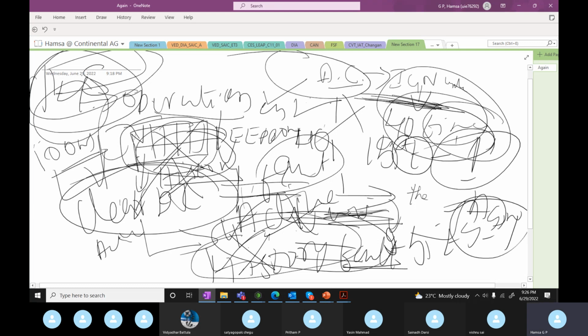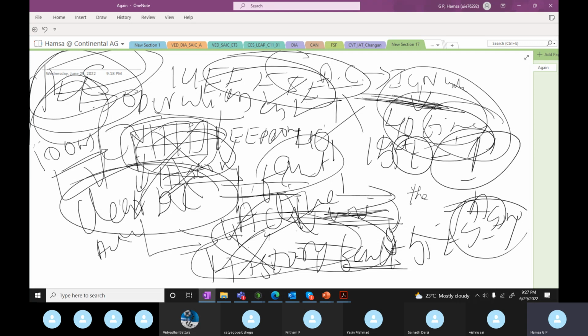This is done by service 14 with FFFF. FFFF means you are not specifying a particular memory, you are not telling the ECU to clear the memory of one particular DTC. FFFF means you are clearing every memory wherever DTCs are stored. But any fault condition that still exists will be present because it is an active fault. Faults that were present in the previous cycle and whose conditions are no longer present, also called history faults, will be removed. That is done by service 14. Clear?